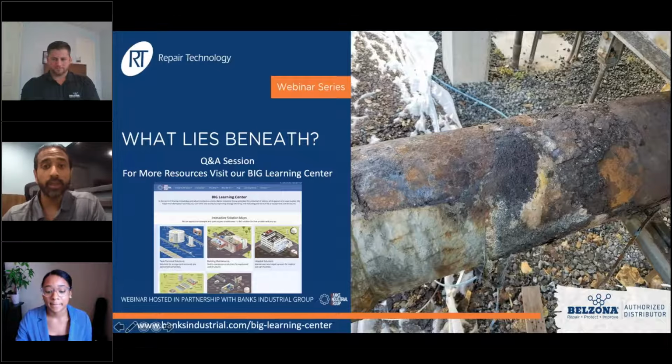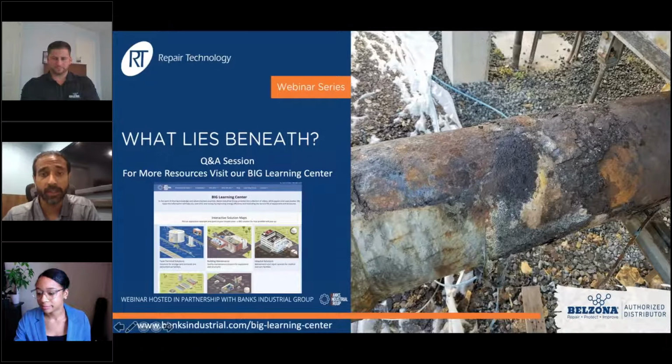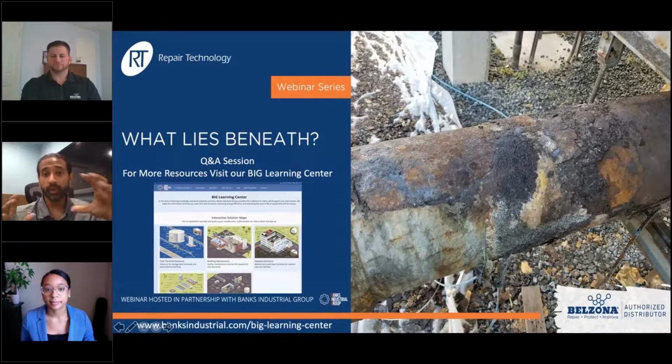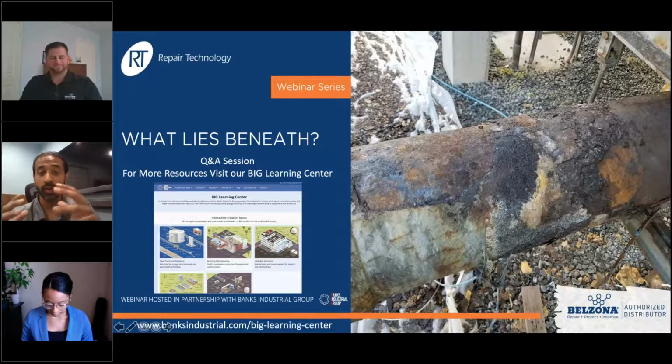Well, yeah, absolutely. And when we talk about CUI, and really when we talk about anything that's about PSM, it's always about the entire encompassing plan. So what is the result of the inspection port being where it is? It's identifying the conditions we talked about. Maybe you have between 150 and 300 degrees. You know that you have insulation around that particular piece of equipment. And so the logic drives and says, hey, this is equipment I need to be paying attention to. So that's why that inspection port exists there, right? It's not just for the internal part for the corrosion, it's also to check externally.